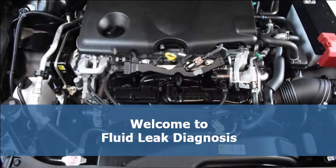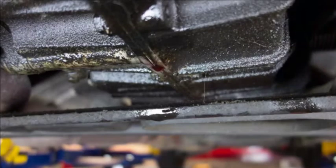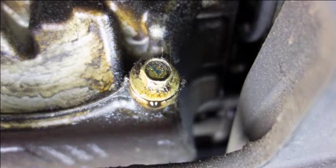Engine oil leak diagnosis may be easy to isolate on a vehicle with low mileage and a normal amount of dirt buildup. High mileage engines with leaks that have been ignored can have so much dirt built up on the outer engine components that finding a leak may require cleaning the engine first. There are two types of oil leaks: pressure and non-pressure. A pressure leak can spray engine oil over a wide area in the engine compartment. Non-pressure leaks usually drip downward over time.